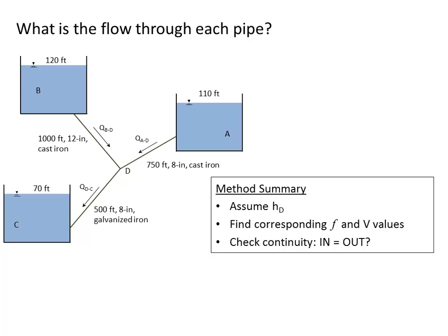What is the flow in versus the flow out at D? And we knew that our solution had converged when two criteria were met. One was that the flow rate in equaled the flow rate out, and the other was that within each step, the F values weren't changing any longer, or that the change was extremely minor, that we had converged on both an F value and on flow rate in being flow rate out. So any questions about that general approach before we move on?